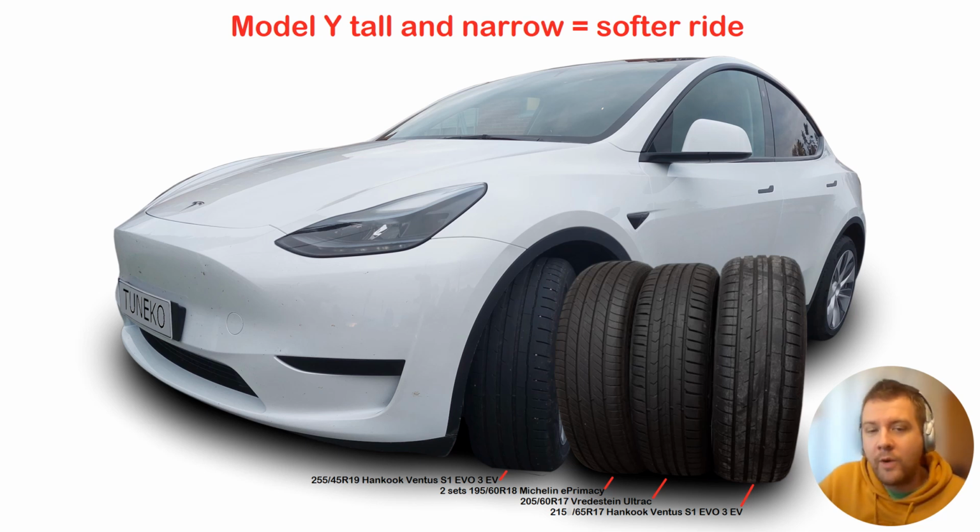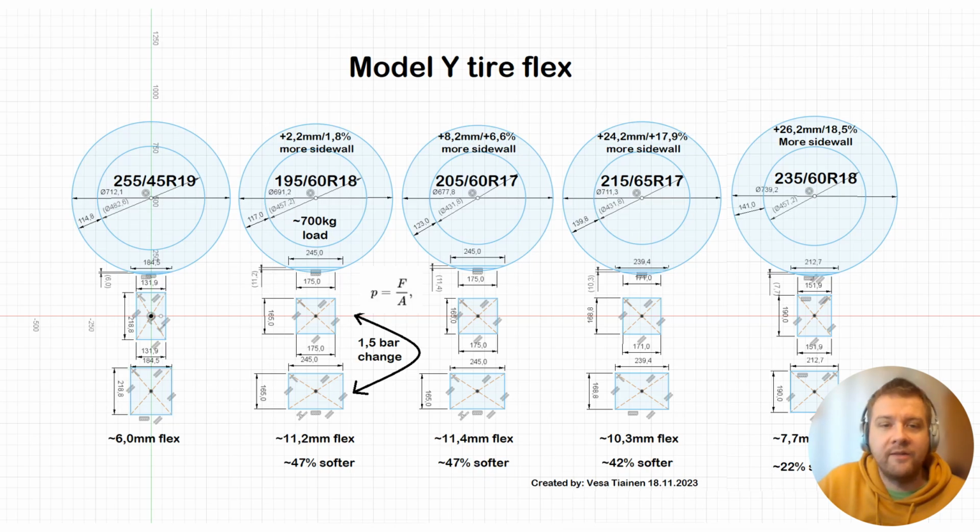The Tesla Model Y has 255mm wide tires from the factory. If you just install higher profile tires with the same width, you won't get a much softer ride. It will make it a little bit softer, but not a lot. If you install 195, 205, or even 215 wide tires, you will make it much softer. And here's how it happens.